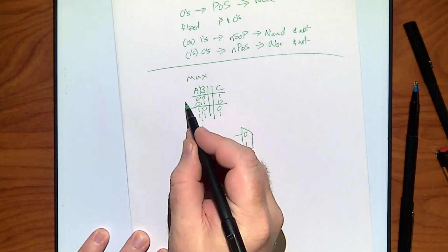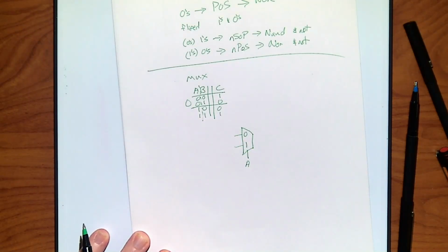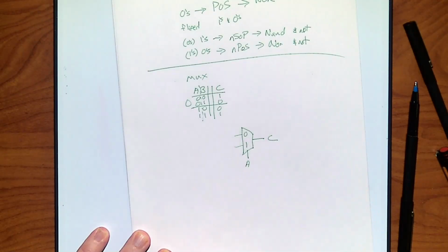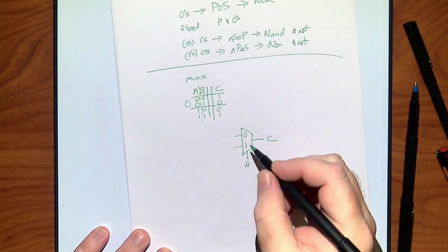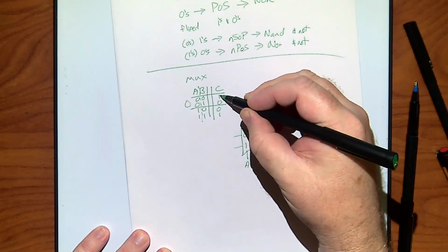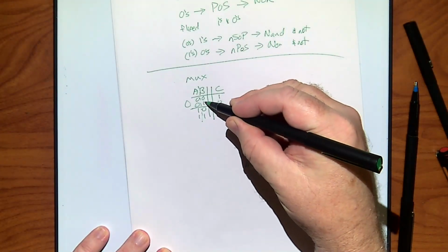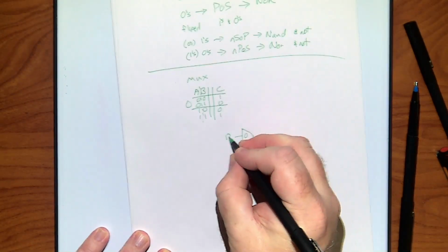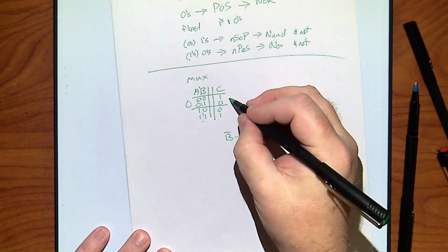That's my two options. If A is a 0, now my output needs to be C. That's what we're trying to design for. If A is a 0, I'm coming through this line. So we look at this, it's a 1, 0. How does that relate to B, the only thing I haven't used so far? It's not B. Boom.